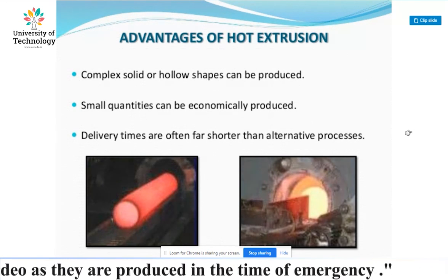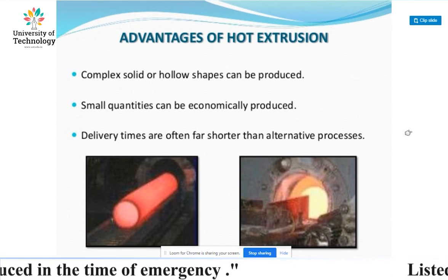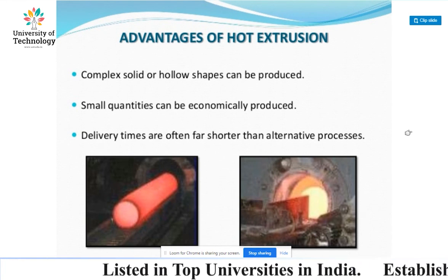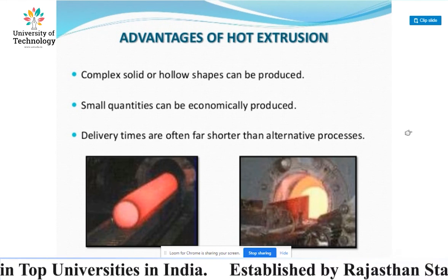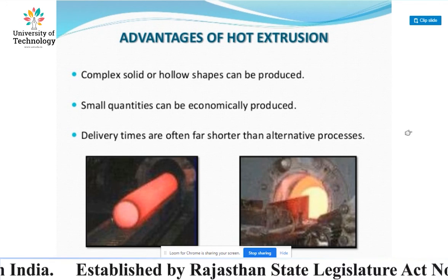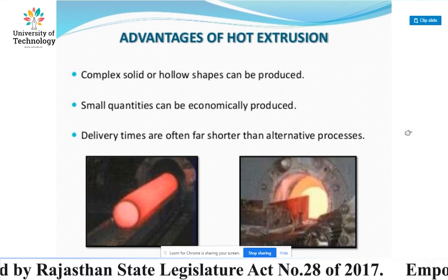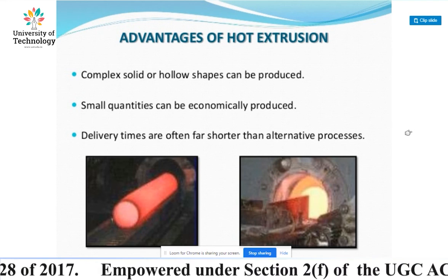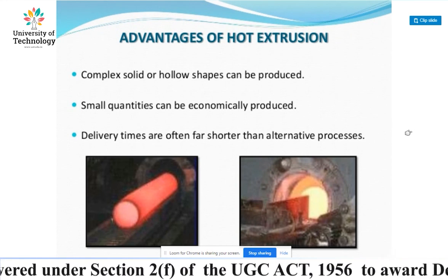Advantages of hot extrusion: complex solid or hollow shapes can be produced by hot extrusion. Small quantities can be economically produced by hot extrusion, and delivery times are often far shorter than alternative processes.